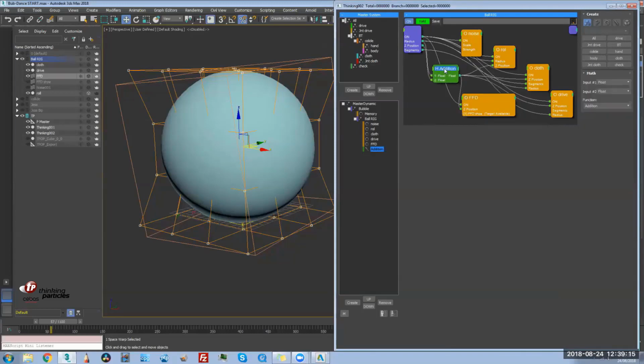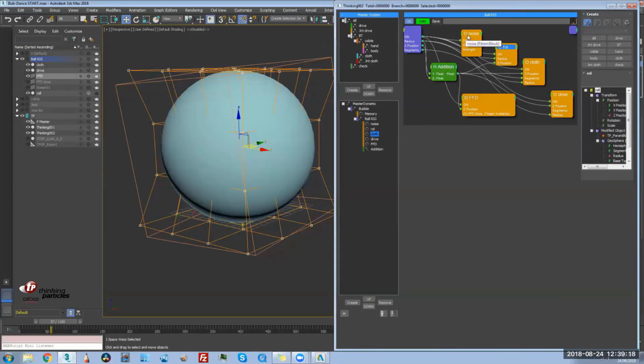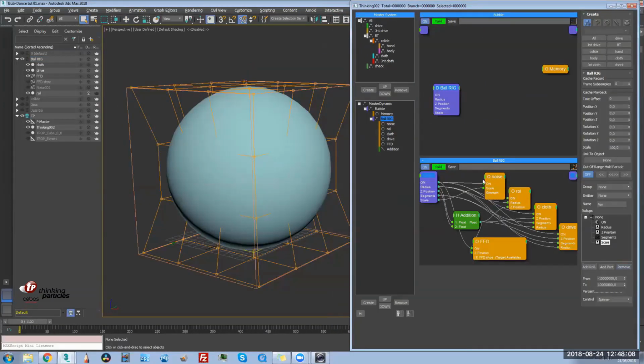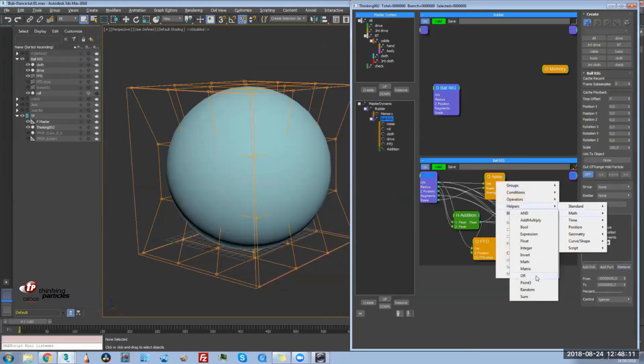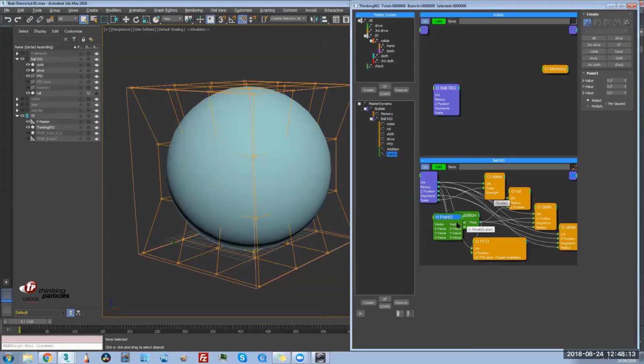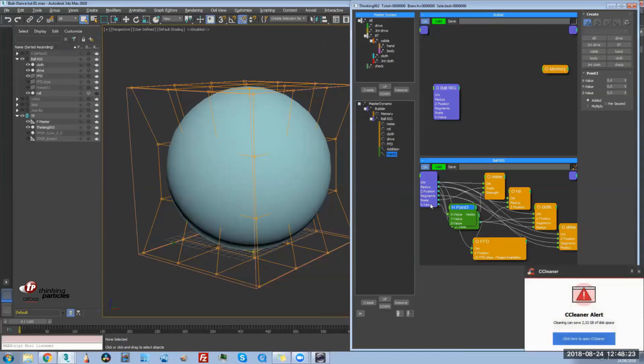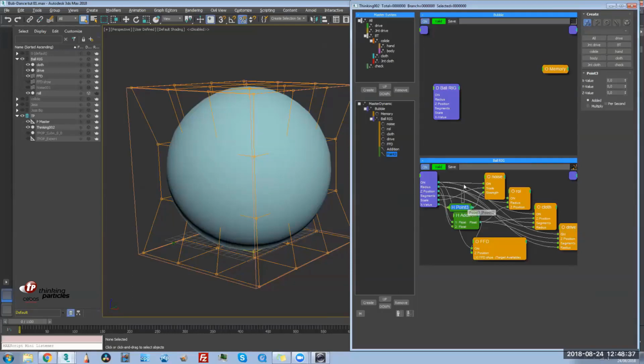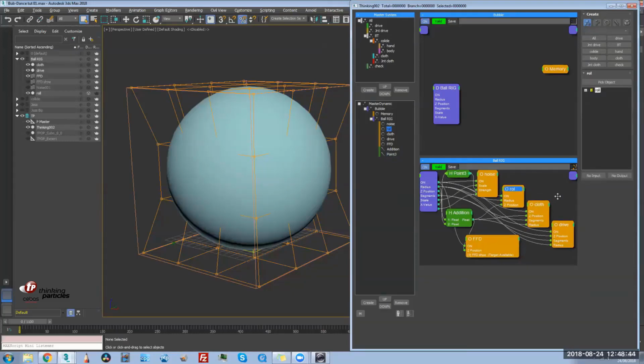So we go to control the strength, the scale, and the velocity of the noise space warp. About the strength, we need to create one more node. It's a Vec3 math node because the strength is a vector, so it needs 3 values. We will use just one value, and we clone the same value on the other 2 axes. So we will have a unique parameter to control the whole strength. And let's go connect the remaining elements.